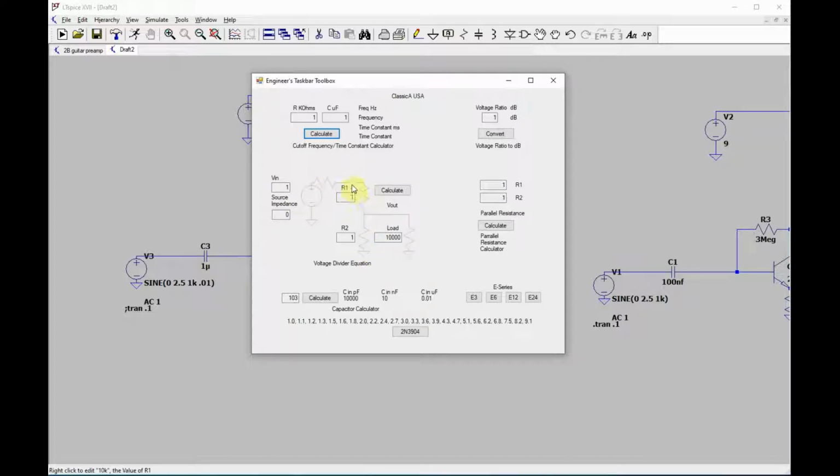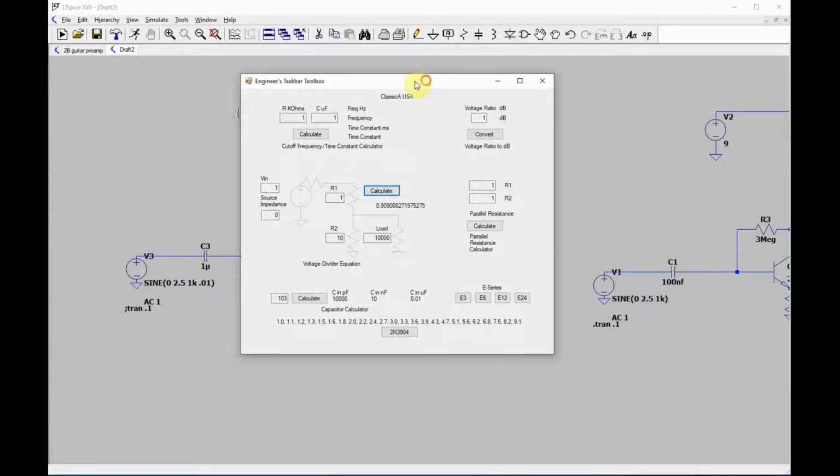The input impedance and the output impedance are forming a voltage divider, and so there's going to be a drop in voltage. If you make that ratio like 1 to 10, you don't really lose that much. In fact, here we can make that 1, make that 10, and you've got 0.9 of the signal coming through. This is a calculator I made, by the way.